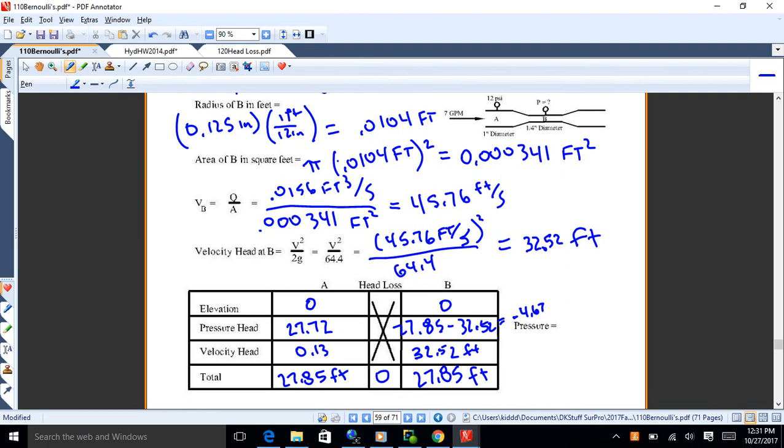Yeah, creating a vacuum, okay? And see, that's the whole purpose of this thing, because it's a chemical feed. So you create a vacuum in that narrow orifice. Well, it isn't quite the right word, but it pulls the chemicals into that flow, okay? And that's what you want it to do. That's a chemical feed. Two places I've seen this commonly used are, one is to pull something in, like a chemical feed. And the other thing I've seen it used to do is to evaporate something, because in a vacuum you can evaporate fluids more easily.